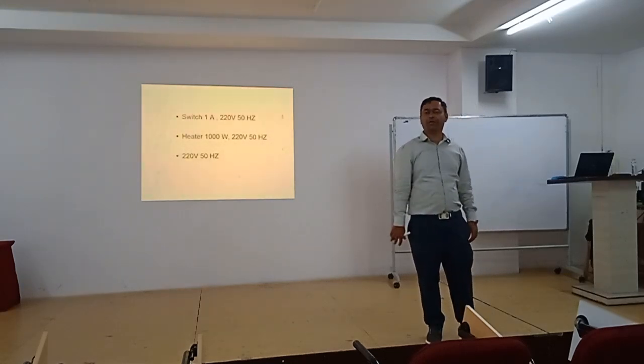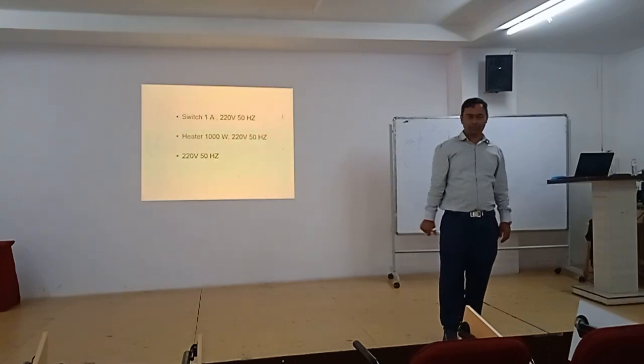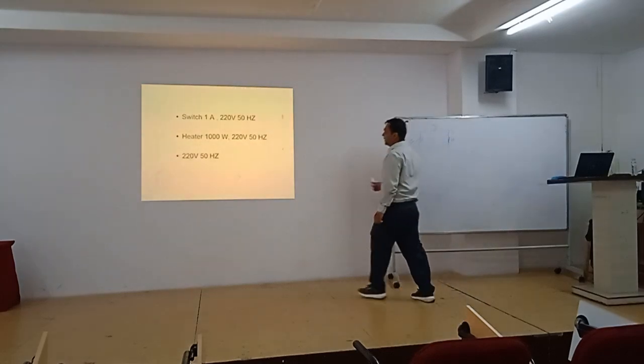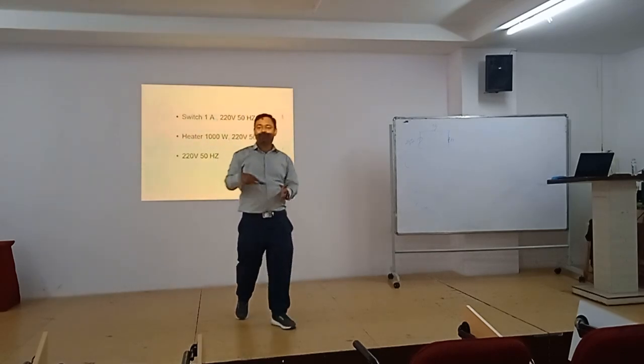It won't work at all. The reason is, as soon as you switch on, after some time the switch will blow. Why? Because 1 ampere is the maximum current that your switch can carry.